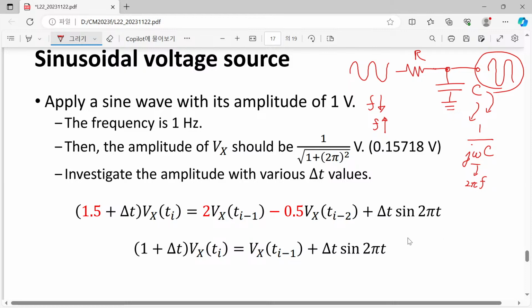So the steady state form of our V sub x is simply given by 1 volt, the amplitude of our input voltage, times 1 over j omega c in series with the impedance of 1 over j omega c and r.